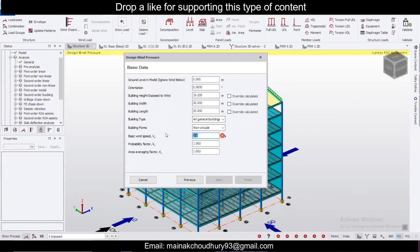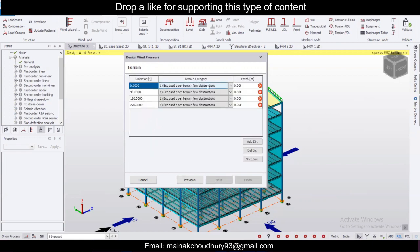The basic wind speed as per the code, as per the region you'll do. That's 50 meter per second here, and then click on next. And here there is a table in the IS code according to which you can select the terrain here. I'll go with open terrain with scattered obstructions. Okay, so I'll go with type 2 of the code here.